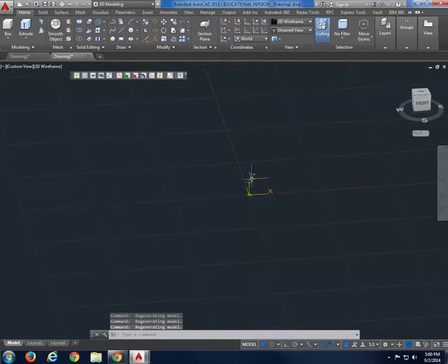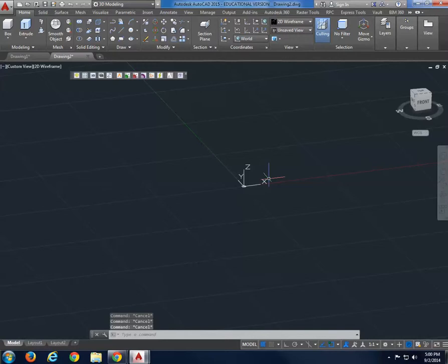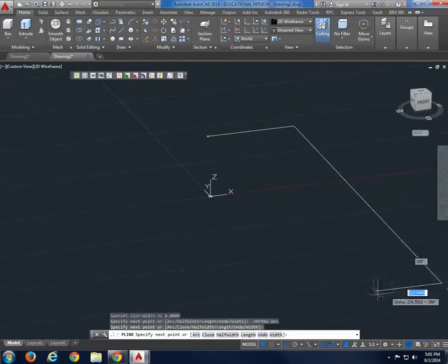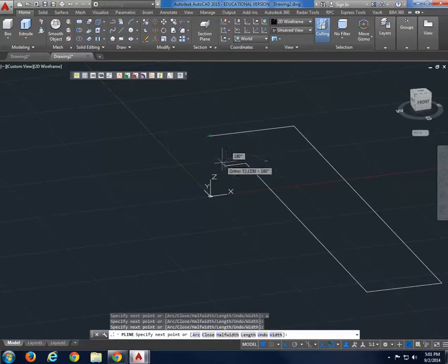It's similar to Revit, so if you learn now and you get happy with the Shift center button, you will be happy in Revit later on, okay? So, at this point, you can still do exactly the same stuff in terms of 2D. For example, PL stands for polyline, F8 for orthogonal, and you can still do your snapping tools, etc., etc.